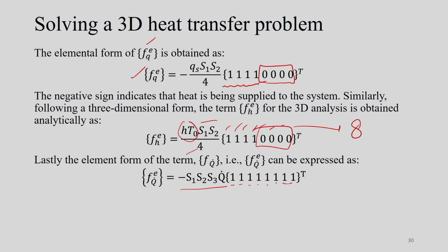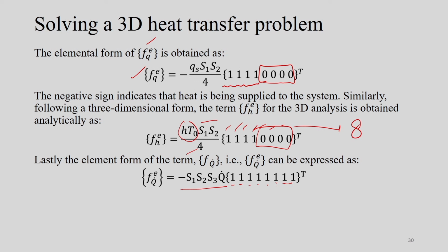Once you construct all the different matrices for a particular element, we have to look into the fact that not all the elements belong to the surface. For elements that belong to the surface, the contribution from the surface has to be there. But certain elements are inside the volume, so those elements do not contribute to the surface interaction. In that case only the contribution from the volumetric term will be there, and no surface components will be there for that element. Looking at all these aspects, for one particular element we calculate all the components: the conductivity matrix, the convective terms, and if there is a tangent term, we can consider all those matrices.